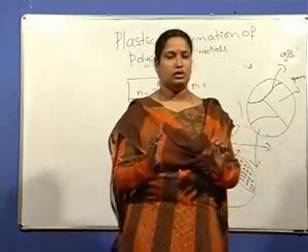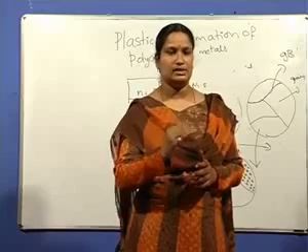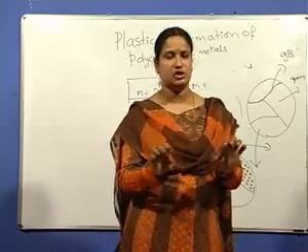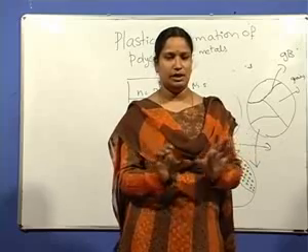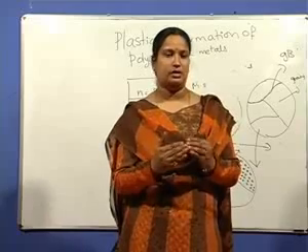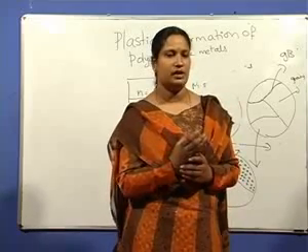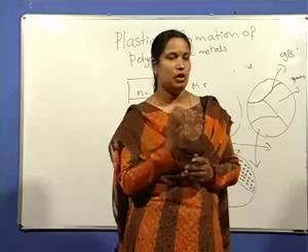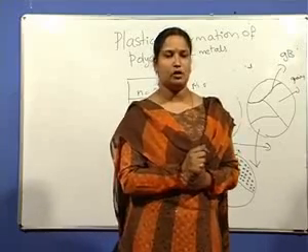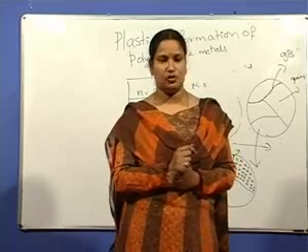So the load is controlled. The load is given in increments by means of a load cell, and the extension or the elongation that takes place in the metal is read by means of a small device that is called strain gauge. So, a plot of stress versus strain.